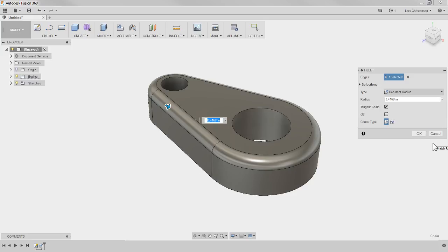So this is what I would call, if you are fairly new to Fusion, the shortcuts that you should feel pretty comfortable with. So L for line, escape key to get out of there, the delete key to delete things, Control Z, undo, that's always good, but also remember it's up at the top there. We got C for circle, D for dimensions, Q for press pull, and then those construction lines with the X. That's the beginning stages of what I think you should feel comfortable with,